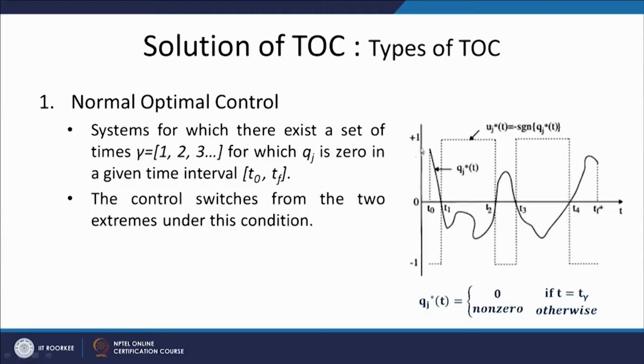and now if you see here, if this is the variation in the qt, what is our logic? If qt is positive, my control will be negative. So, I will get a negative control up to the point where it crosses 0. As this crosses 0, only at this moment the qt will cross 0 from its minimum value to maximum value, which will be the switching point, and when qt becomes negative, my u will be positive.